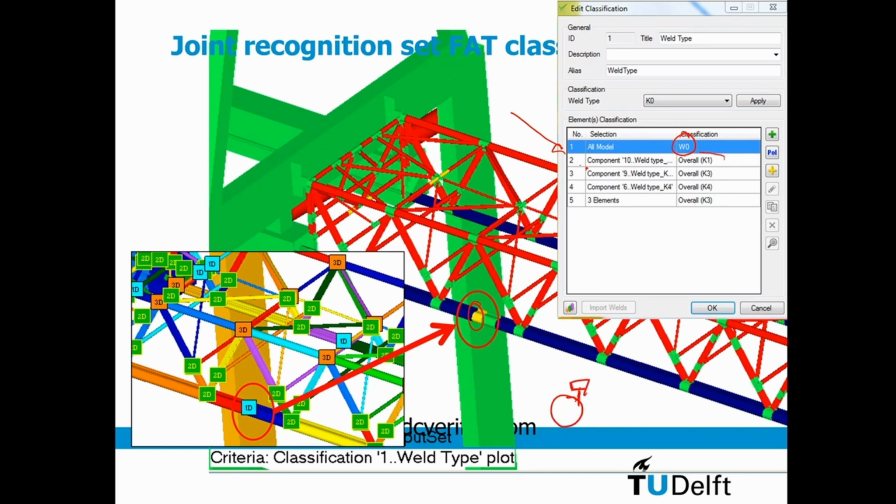That is in this case a tube with the rail welded to it. That is K1. And for all these connections where I have welding, that is always a K3. And there is one spot here which is a K4, because that weld is only on the outside. If it is a tube which you weld, you can only weld it from the outside, so the weld quality inside is not known, and that's considered a K4.